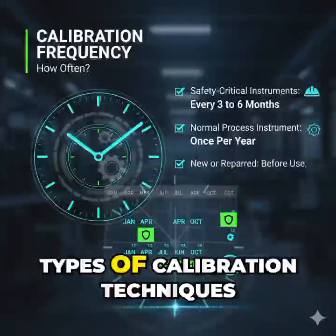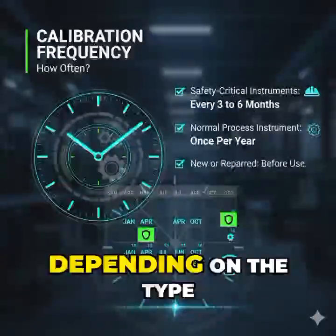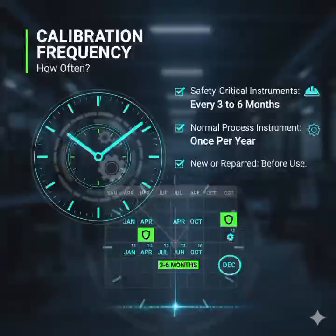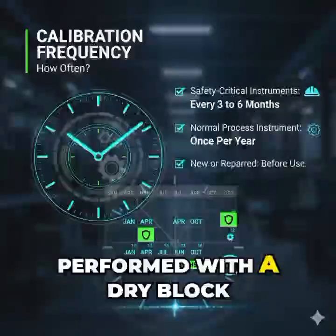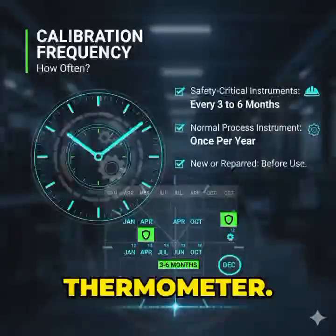4. Types of calibration techniques. Calibration methods vary depending on the type of instrument. Let's look at some common techniques. Pressure calibration, done using a dead weight tester or a pressure calibrator. Temperature calibration, performed with a dry block calibrator or a liquid bath, along with a reference thermometer.